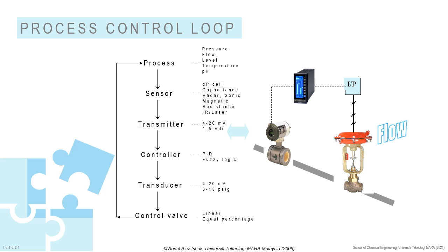The sensor and transmitter are the devices that conduct the measurements and conversions of variables into analogous or electrical information. The term transducer may be used for a device that converts a signal from one form to another, for example converting a voltage into a proportional current.